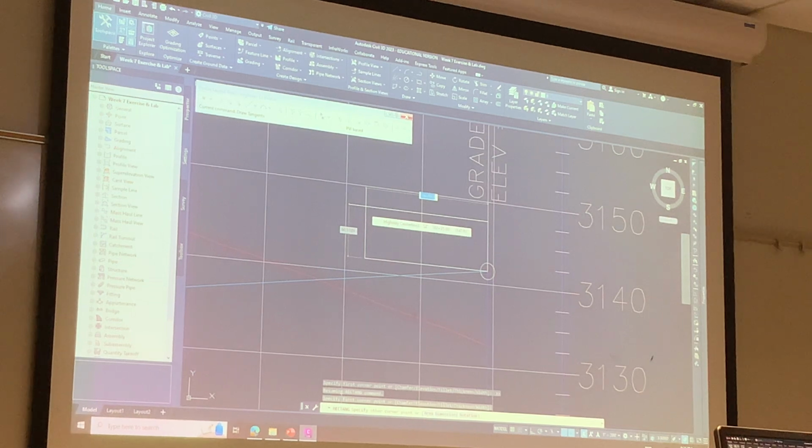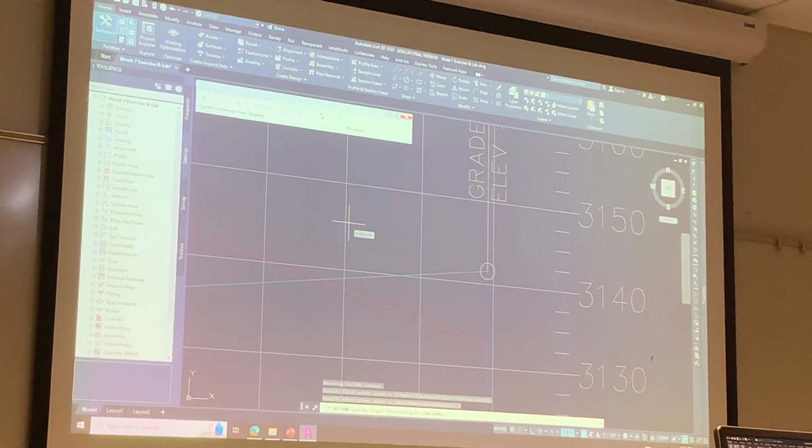However, if you choose to use the dimensions option down here, or by entering D, enter, you can enter just the absolute value of those X and Y. For all of us, it'll be 100 in the X direction. In the vertical direction, the Y, I want a slope of 1.1%.